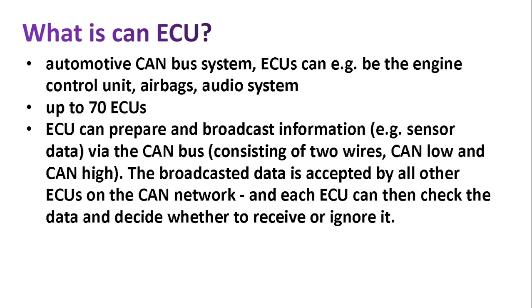So this signal is passed from the ECU throughout the cable to all the features. At that time only the door glass unit is going to accept that signal, because this 111 ID is assigned only to the door glass, not other features. The other features will decline that signal which is received from the ECU.